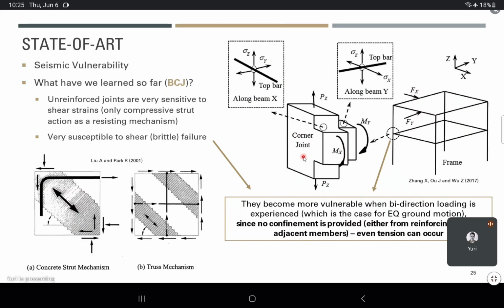And by decreasing confinement, you lose bond strength. Especially when you have a lack of stirrups in the corner joints and plain bars, you can have a premature shear failure because the shear compression action is the only thing that promotes strength in the core joint.